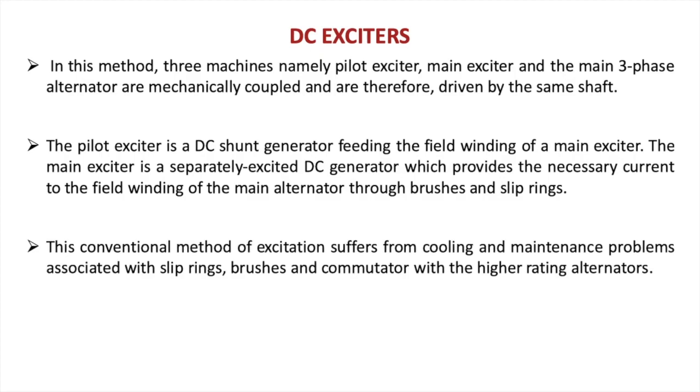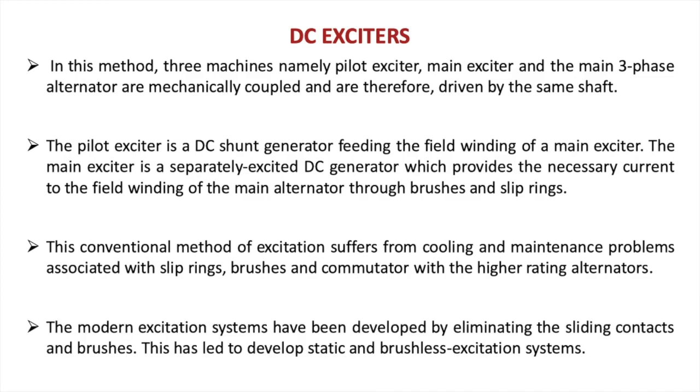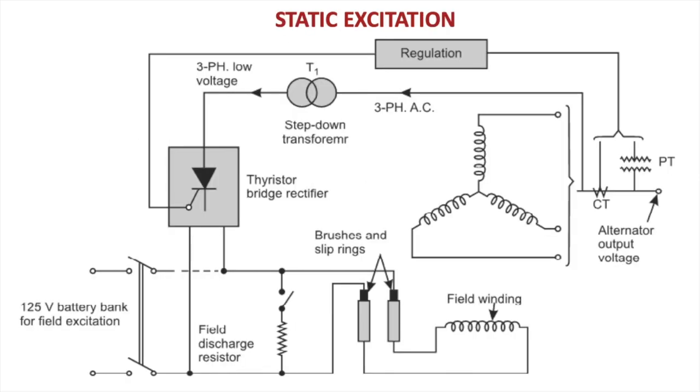This conventional method of excitation suffers from cooling and maintenance problems associated with the slip rings, brushes, and commutator with the higher rating of the alternators. The modern excitation systems have been developed by eliminating the sliding contacts and the brushes. That is, this has led to the static and brushless excitation systems, eliminating the slip ring and brush arrangement. So the static excitation, over here you can see the arrangement of it.